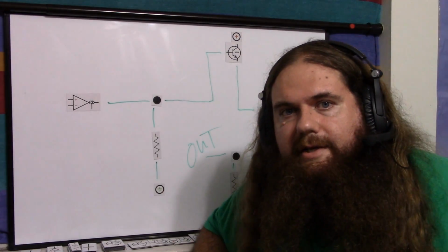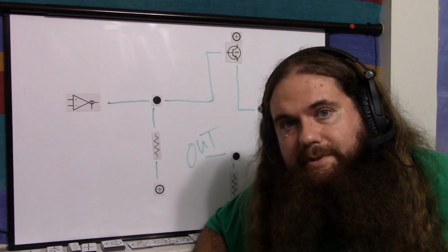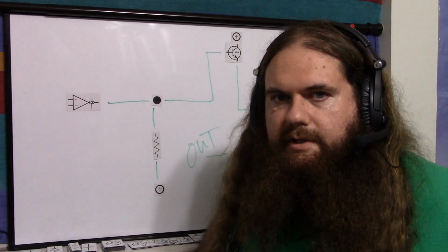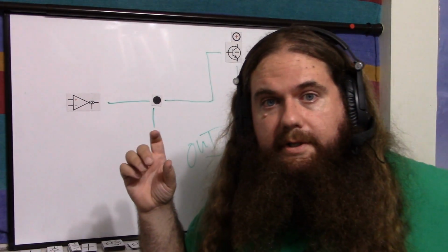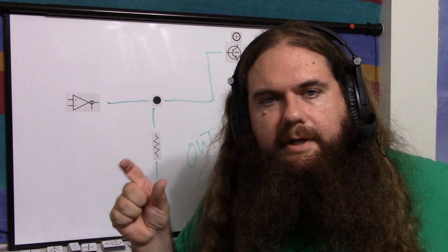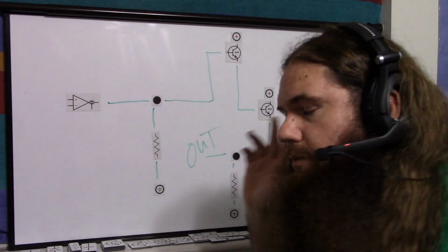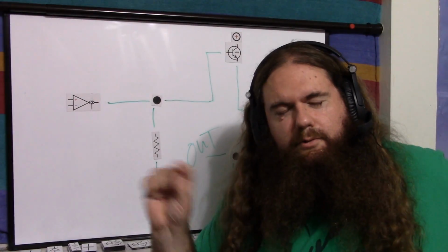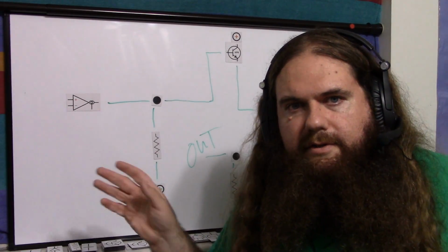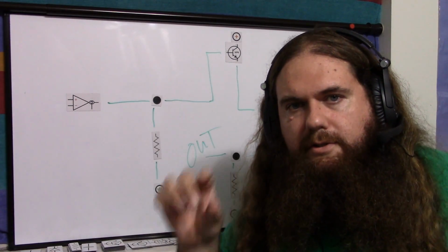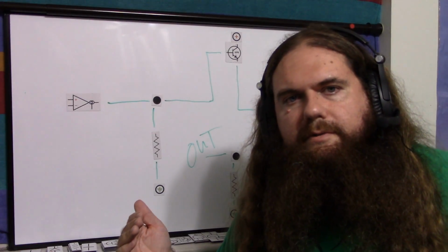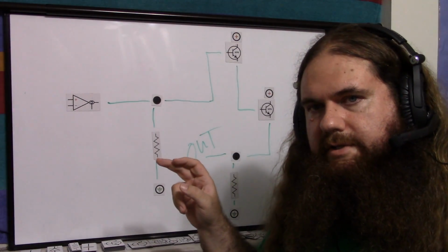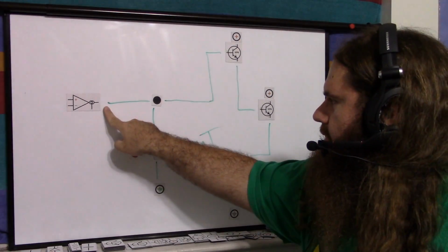Now, the datasheet says with the buffer, you still only get 20 milliamps. So you're going to want to put another power buffer after this, unless you're driving something very simple. But that microcontroller pin, for example, that might have varying impedance reading the analog voltage, well, 20 milliamps is more than that would take. So with this buffer, you could plug that in there, and you don't have to worry about whatever capacitance and other nonsense that microcontroller pin is using to read the analog voltage and convert it to a digital value, because that power is being fed by the collectors of the transistors. The actual load is separate.